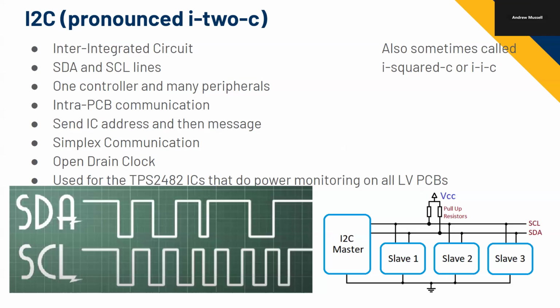Yeah, so when I want to start communication on I2C, I will pull down the data line to say I want to start, and then I'll pull down the clock right after that. And then the clock will basically just toggle up and down. This is also another one: you have to determine the frequency or the baud rate beforehand.